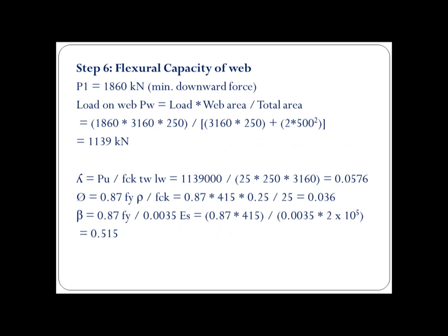Now everything is calculated. The next step is to calculate the flexural capacity of the web, so that we'll be able to calculate the axial load coming onto the boundary element. Or in simple terms, if we are not going for a boundary element, the flexural capacity of the shear wall should be greater than the moment resulting from the loads.